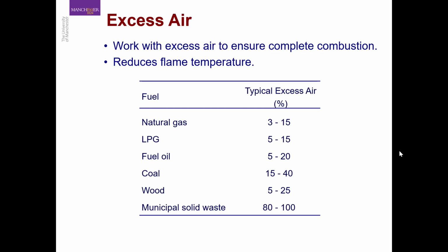Now, depending on the nature of our fuel, we could have a different typical value for excess air. For example, for natural gas, LPG, and fuel oil, you can see that we require a relatively low percent of excess air, but for solid fuels like coal, wood, and municipal solid waste, we need a relatively much larger value of excess air. This is again to ensure better mixing of the fuel with the gas, and then complete combustion.